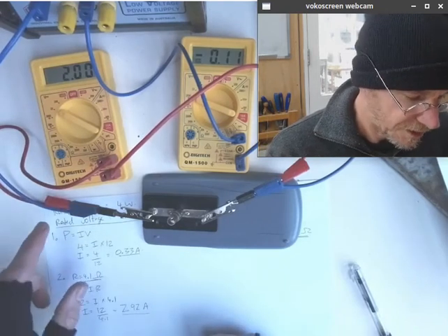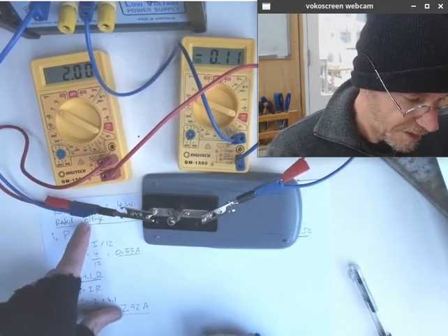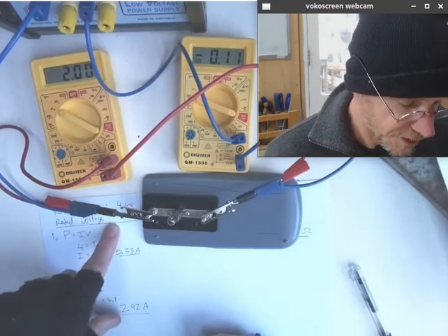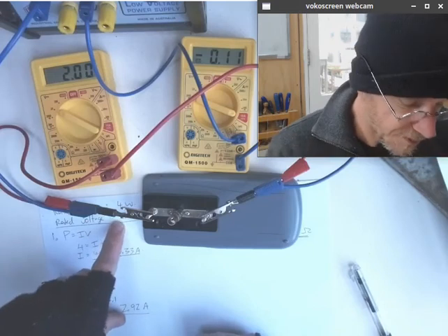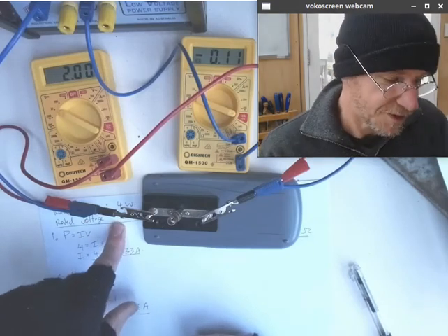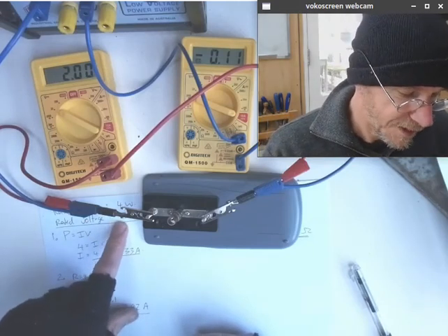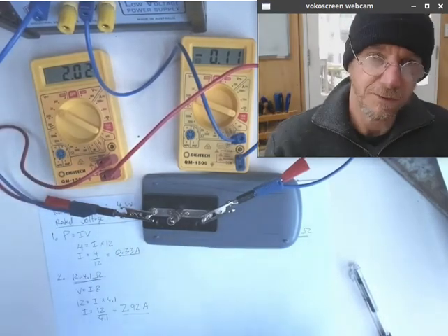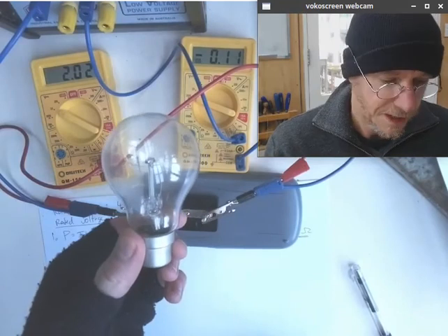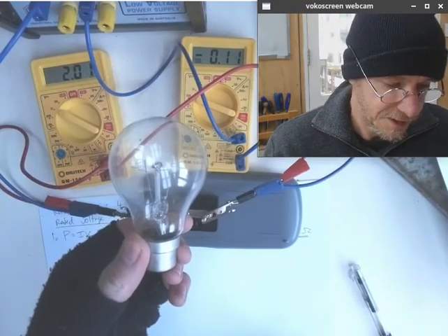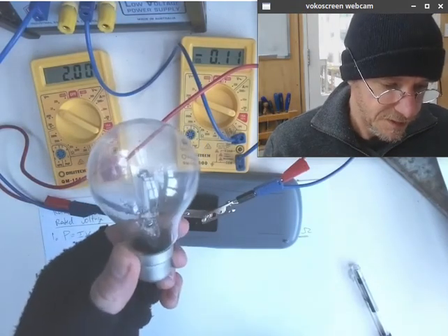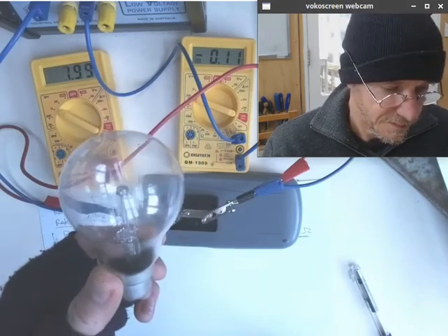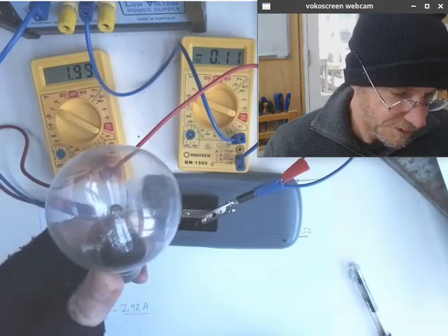For that, you need to look at the manufacturer's rated power or rated current, and for that matter the voltage which they have intended it to be used with, and to only use it with the voltages that it's intended to be used with. For example, applying 12 volts to this light bulb, it won't heat up to anything like the extent it's expected to, and consequently its resistance will be much lower than expected. However, it's still not going to draw very much overall power.